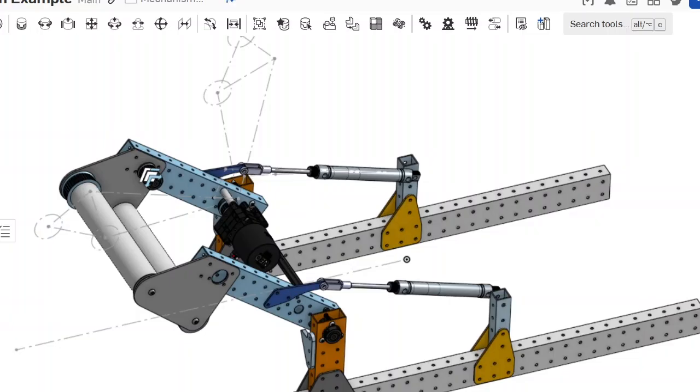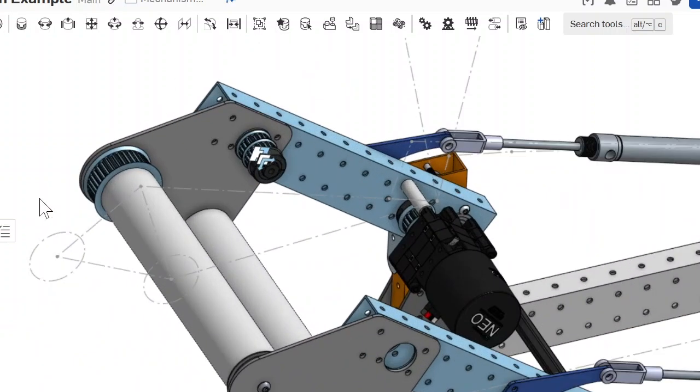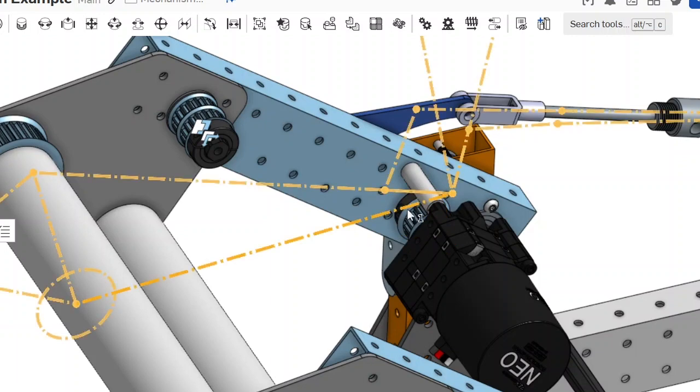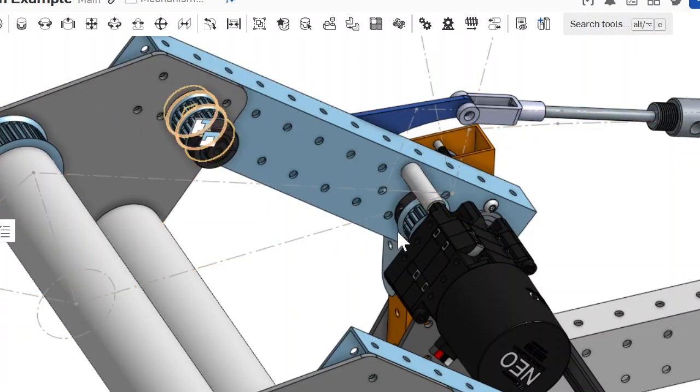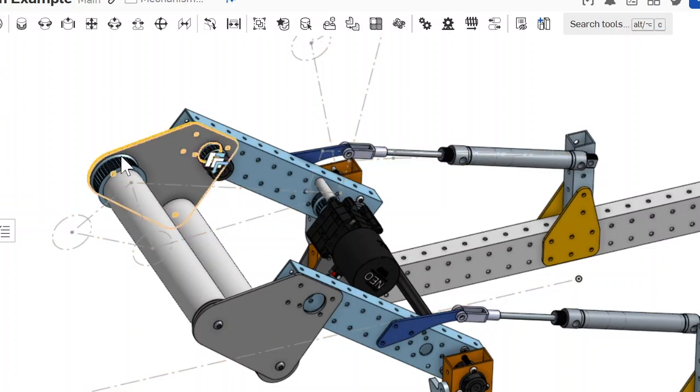Let's go over a quick intro to the design calculator that we're going to use for this season. The design calculator essentially is a spreadsheet that helps you calculate the distances needed for your power transmission runs from your motors to your different systems. So like belts, just like this. How far does this pulley need to be from this pulley in order to have an appropriately tensioned belt?